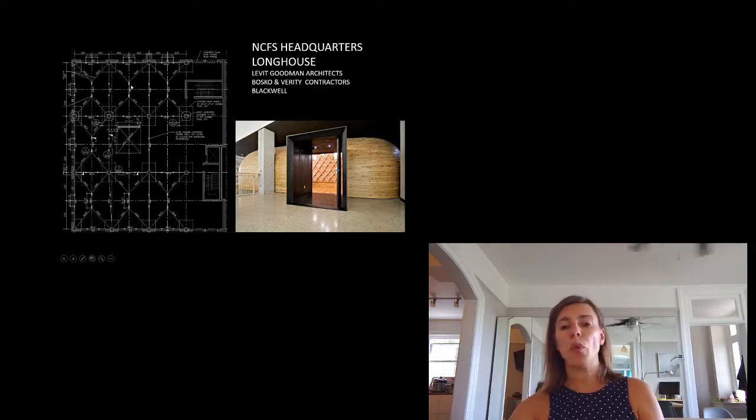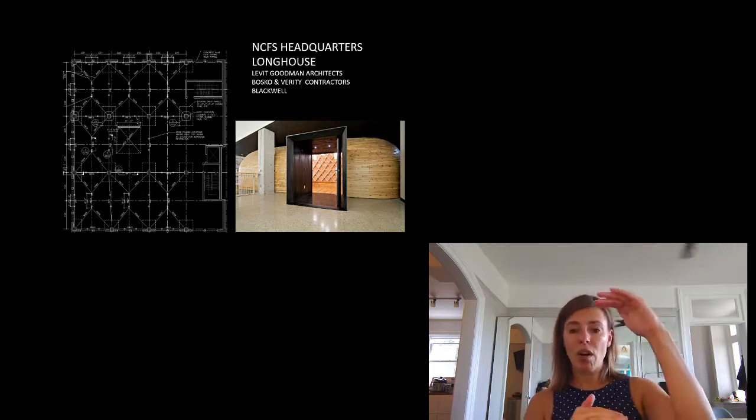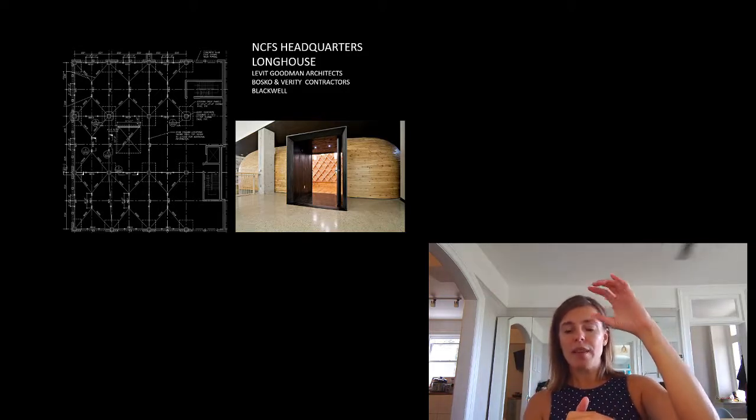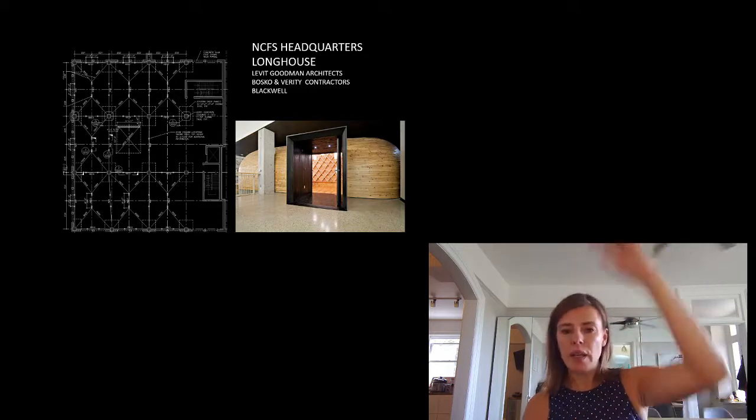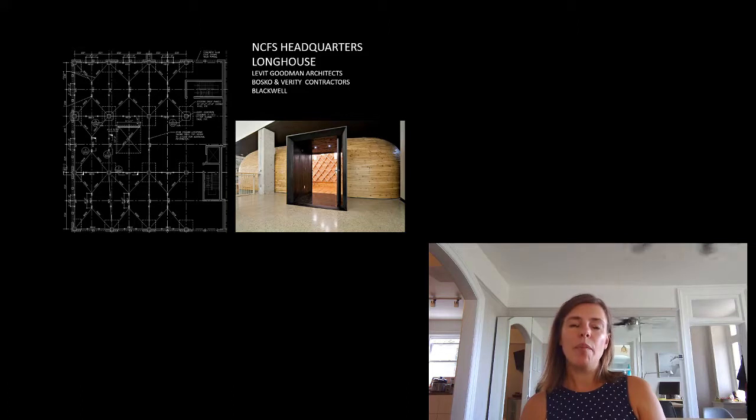We couldn't even reinforce the existing concrete structure. It kind of became a cyclical thing. As we added more concrete to deal with the load, the self-weight of the concrete overloaded the parts at the bottom, including the soil on top. So we needed a system that could essentially unload the roof for the new load we were putting on.